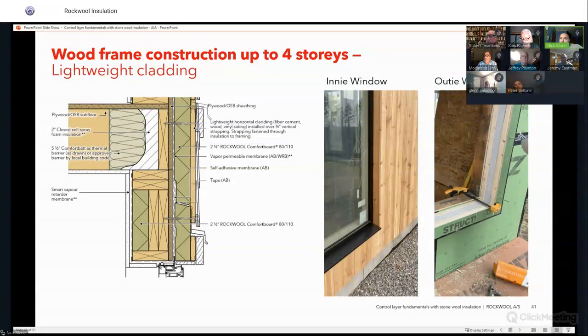Gotcha. Okay. Can I ask a quick question? If you see that slag wool up in an attic of a 1970s or 1940s house, is it still maintaining the insulation value that it had when it was first installed, or would you recommend that it be replaced? Realistically, if you replace it with new stuff, it's going to have better performance. Now, what's there, is it performing? Yes. Is it performing at what it was manufactured at however many years ago? My suspicion is probably not.